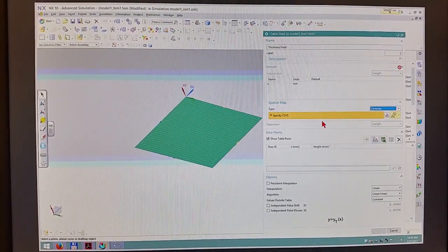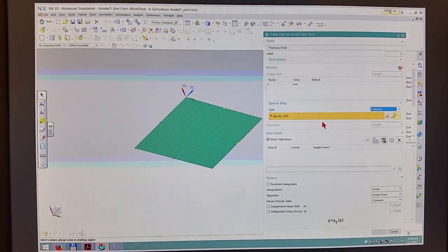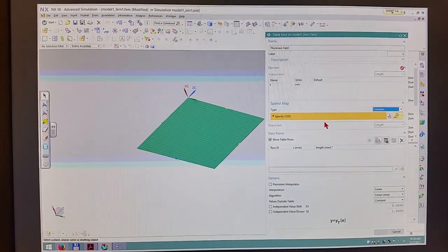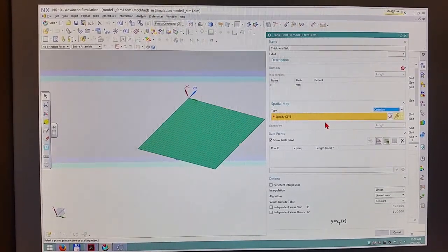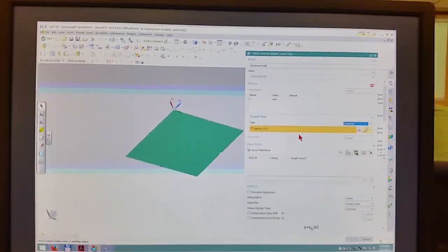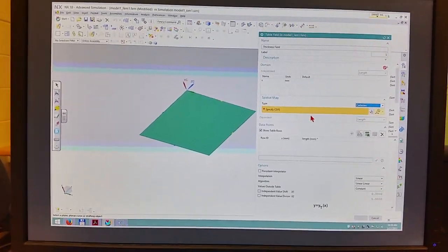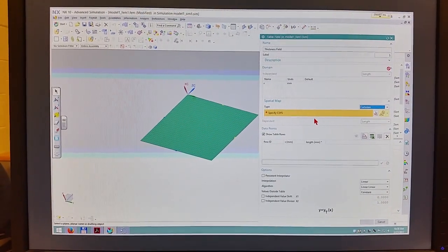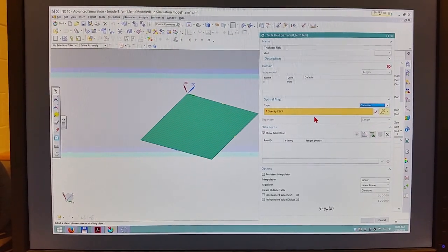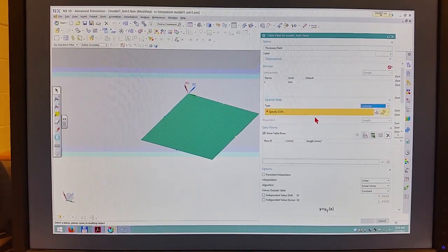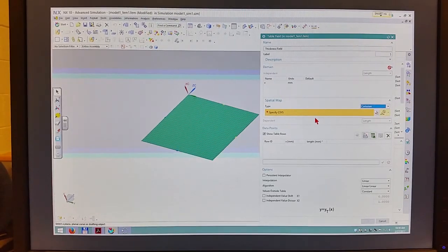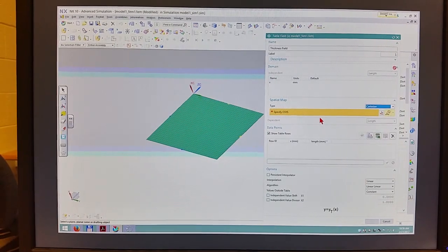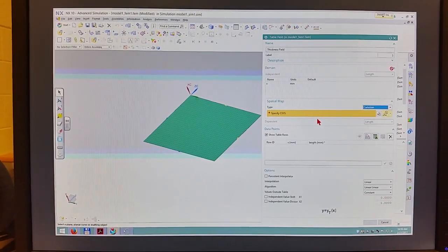So now it's waiting for me to pick a coordinate system. I can go in and try to define a coordinate system, but it wants to create one, okay? The thickness is very picky. Most other things we can create a coordinate system and then pick our coordinate system. Like we did for the beam, remember when we had the beam sliding along that angle, we went and defined our coordinate system and then we defined our boundary conditions based off of that coordinate system. So here with the thickness, it really wants to create the coordinate system in this step. It doesn't want us to go define one and then try to pick it. Okay? If I'm just defining some general function, then it's easier to do that.